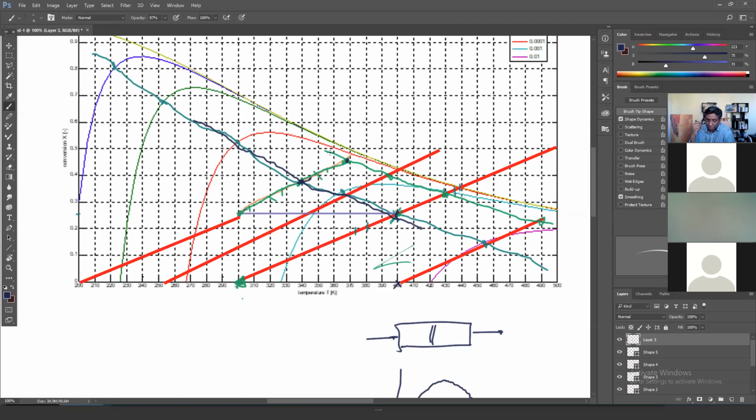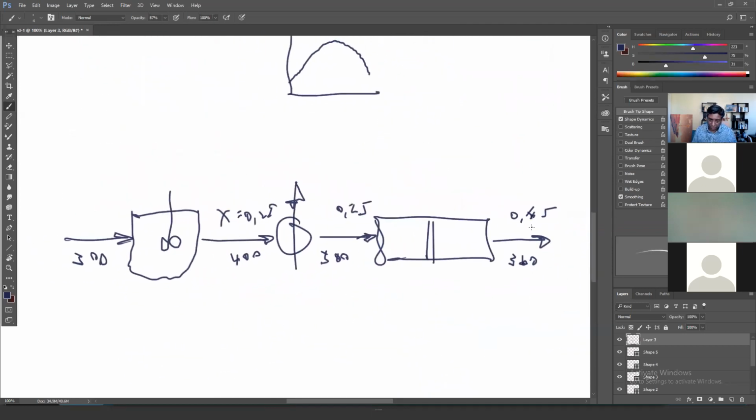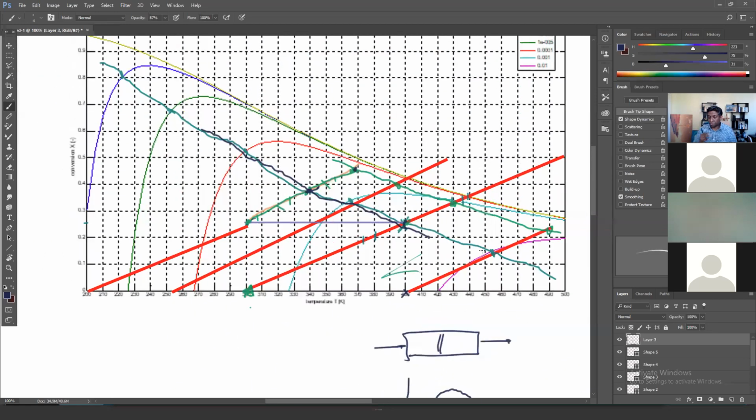And as I say, please go ahead and show that. So in terms of your actual accomplishment of a final 0.45 and those temperatures, you'll see no difference. But in terms of the volumes, VCSTR and VPFR, you will likely get a higher volume if you switch those around.